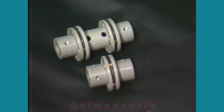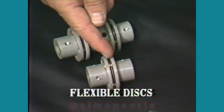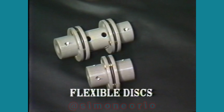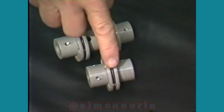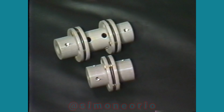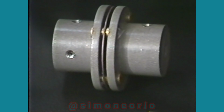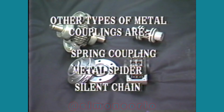Another popular all-metal coupling is the flexible disc. These discs are used in stacks or packs, as they are called. The steel discs are used in both single and double series, as you see here. This is the first all-metal coupling that has been demonstrated which does not require lubrication. There are many other metal types of couplings, such as the spring coupling, the metal spider, the silent chain coupling, and so on.